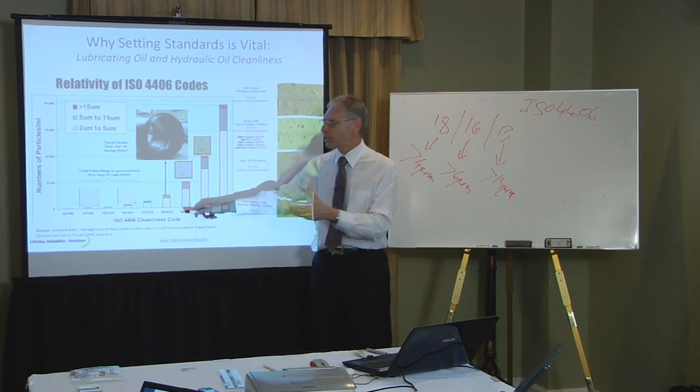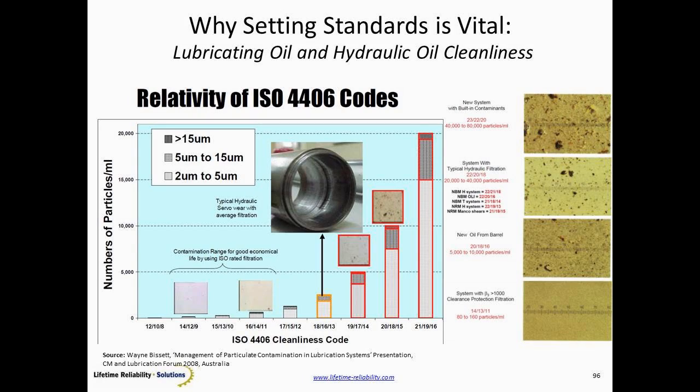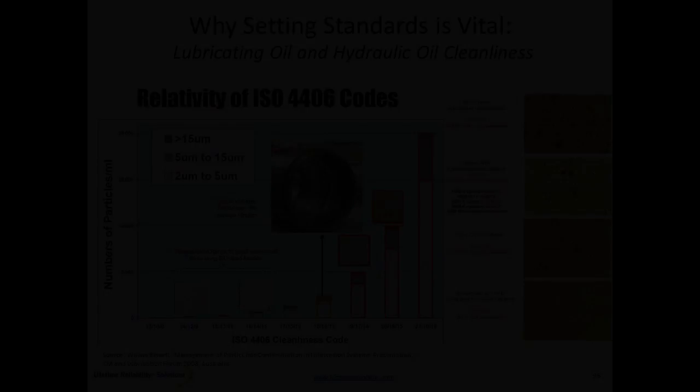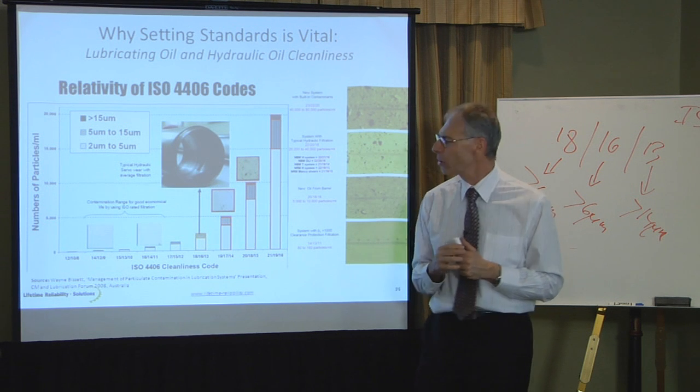The manufacturer of the equipment said you must have nothing more than that, and that's what it was. And that count caused that. So this lubricant is too dirty to get high reliability out of this machine, even though the OEM said it's okay. And what we'll find is the OEM's requirements are not good enough for reliability. The OEM's requirements are acceptable, tolerable, sufficient, but not good enough. They aren't in that boundary of precision that provides high reliability.